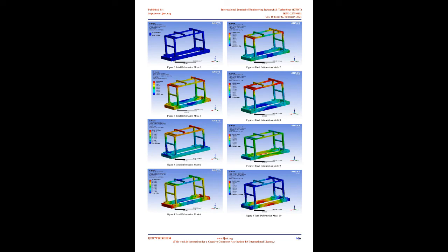Selection of chuck. A 3-jaw drill chuck with threaded fittings was selected as the specimen clamp for the fatigue machine. The drill chuck was selected because it is durable and cheap to procure. The specimen clamp is expected to firmly grip the specimens without allowing for extraneous bending moments during operation of the machine. Also, the specimen must not rotate from the grip or be displaced vertically or horizontally.